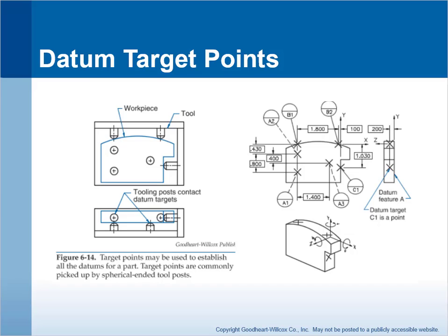I want to talk more about this one in the next movie, but this shows how the 3 points define a primary datum, 2 points define a secondary datum, and then 1 point could define a tertiary datum. So I'm going to pick this up in the next movie.